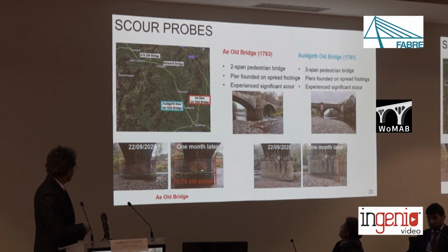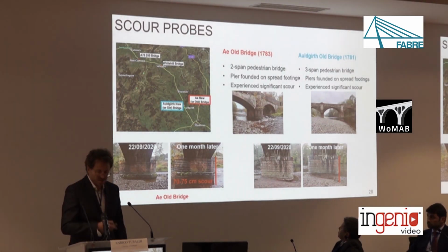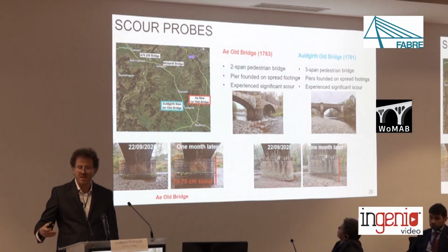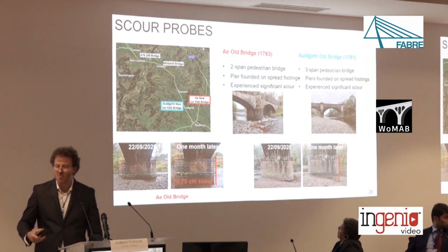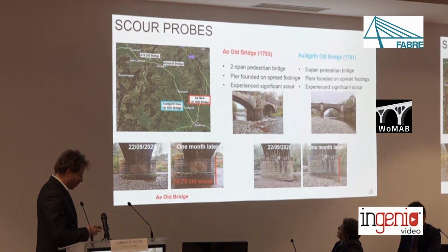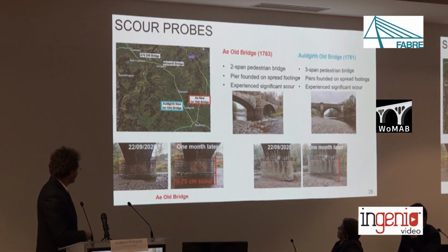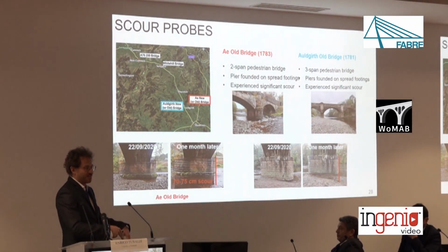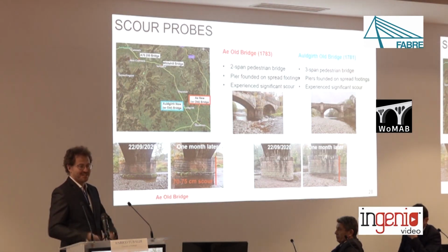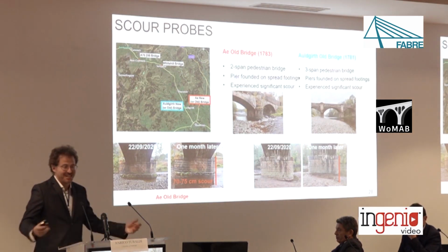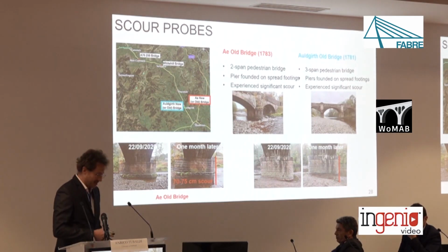And I'm quite excited by the installation of the probe at this bridge, Old Bridge, that will take place hopefully next week. Because at this bridge we know for sure that there is a continuous evolution of the riverbed, and particularly there is a live bed scour with redeposition of sediments after floods. And so when we install the scour probe in front of the pier, we're also going to refill the scour hole. This will be a way to validate the measurement of the scour probe, and also we'll make sure that during the unavoidable extreme weather event that batters Scotland, there will be some scour, and we will be able to detect it.